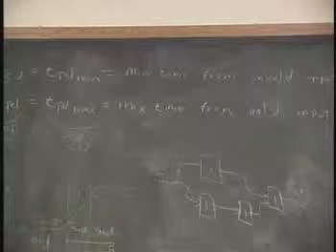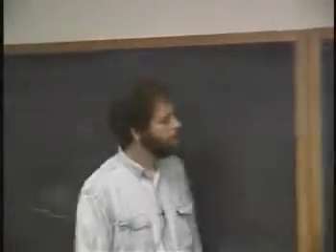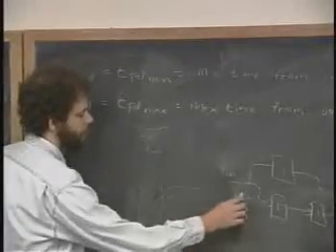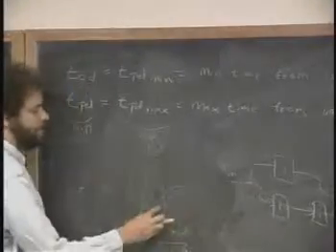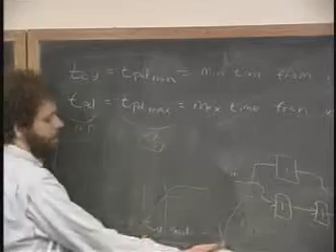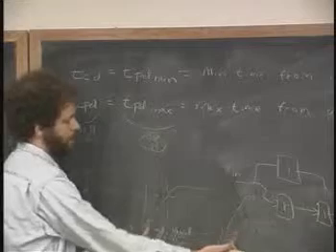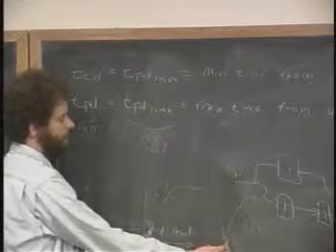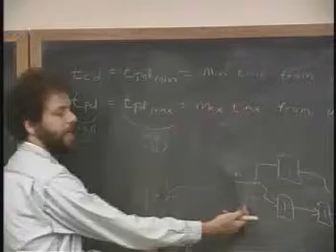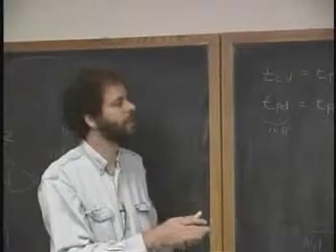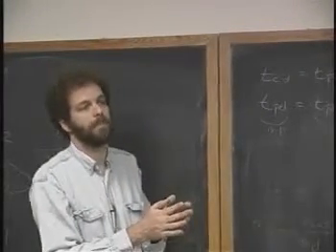Don't we have to get the new valid data in before we can get to the end of the TPD? Well, at the same time, if this is the in and this is the out, and the amount of time they spend in this regime is the same, then measuring from here to here and measuring from here to here would not necessarily give you different times. From invalid in to invalid out, from valid in to valid out may in fact give you the same time. But there is this business where we're measuring the shortest time it'll take and the most time it'll take. So in general, TPD max will be bigger than TPD min.